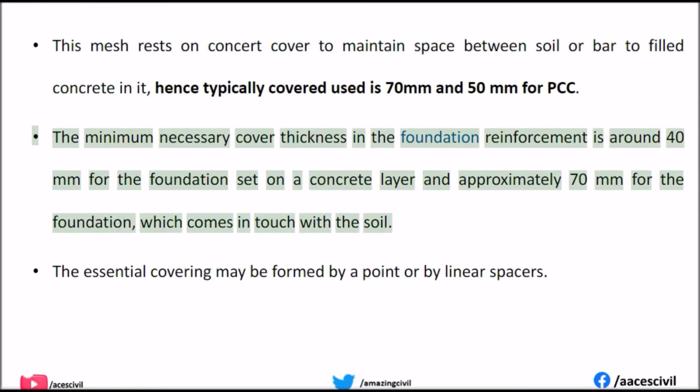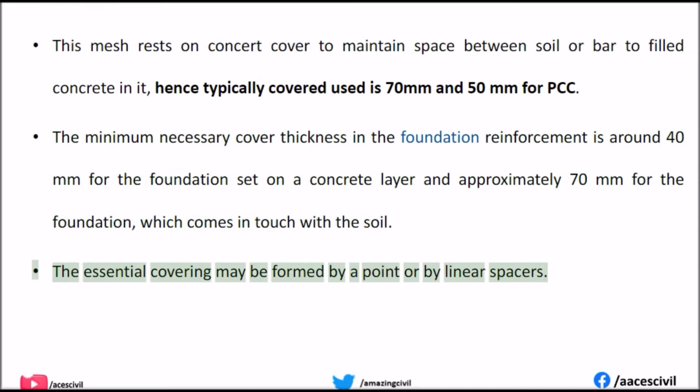The minimum necessary cover thickness in the foundation reinforcement is around 40 mm for a foundation set on a concrete layer and approximately 70 mm for a foundation which comes in touch with the soil. The essential covering may be formed by point or by linear spacers.